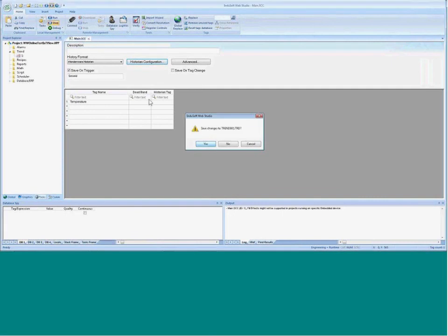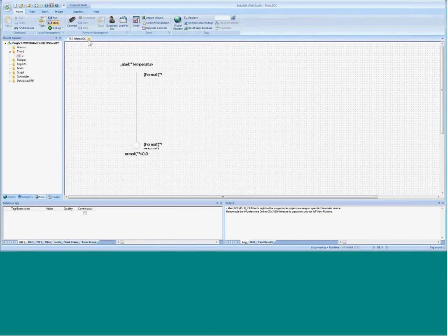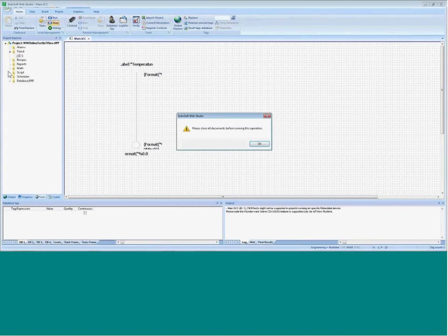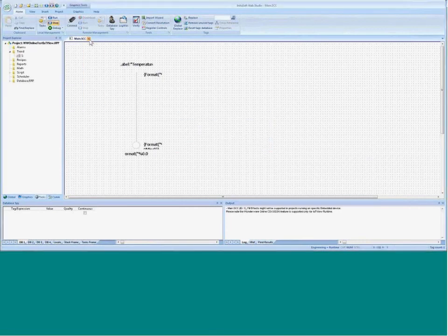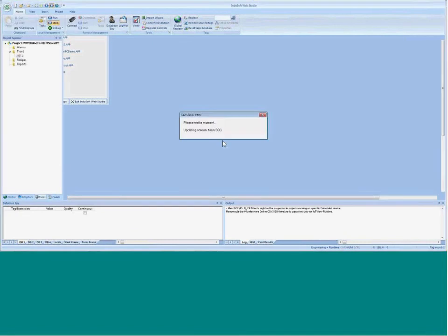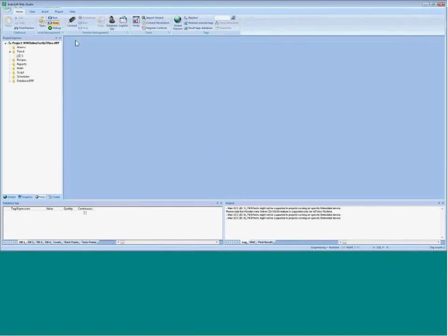So when I save this, the thing that I messed up when I was testing earlier is that this feature is only supported on IoT View. So in this case, since I made some changes to this screen, I'm going to publish my screen here. And I have to load this now into my Raspberry Pi.